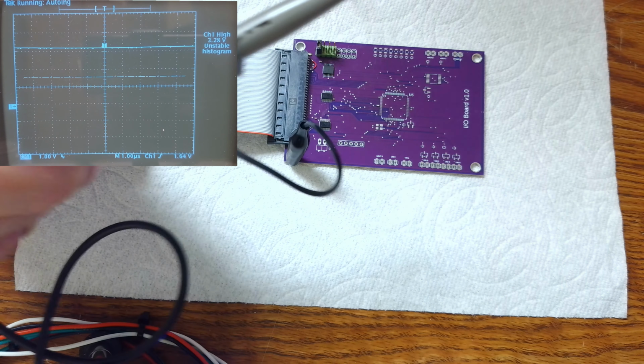And so the idea is that while using the resistor, we can probe the address and data lines, and if it's being driven low by another chip, then it'll stay low because the resistor won't be able to pull it up, and the resistor will drop the voltage across it.